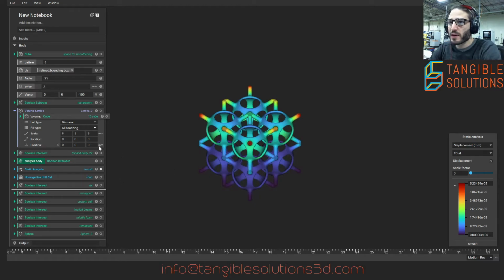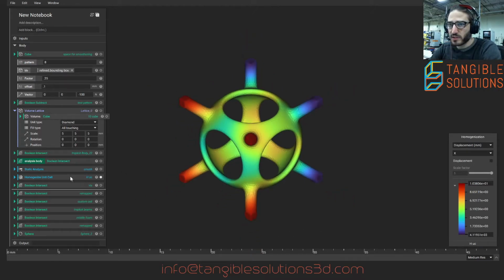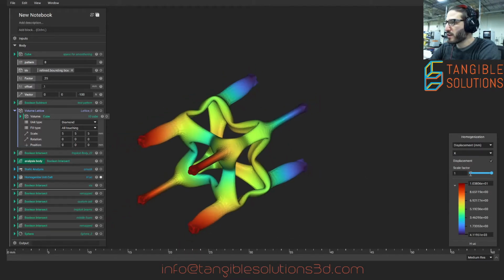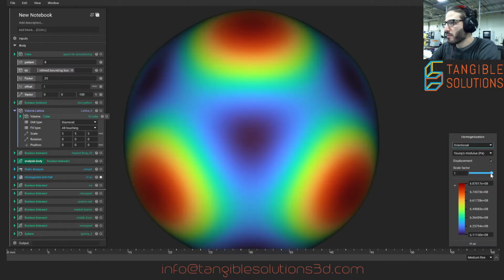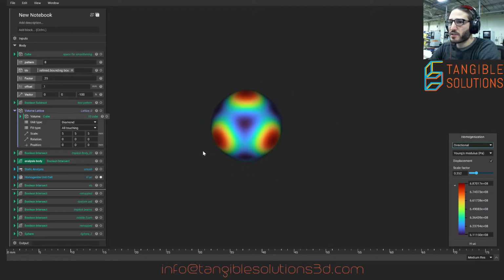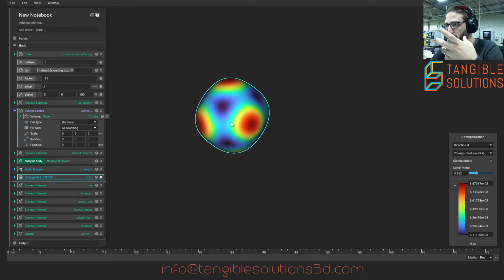The other really cool thing about Modulo is that you're starting with a unit cell, so it goes nicely hand in hand with nTopology's homogenized unit cell. We're getting this unit cell, we can evaluate its properties, we know how it's going to deform, and we have a general idea about its modulus. Because it's built as a custom unit cell, we can then use Modulo to pattern that unit cell after we've refined it.